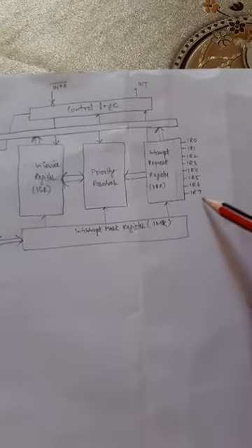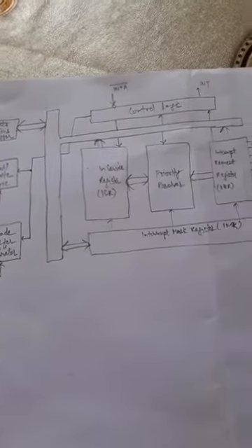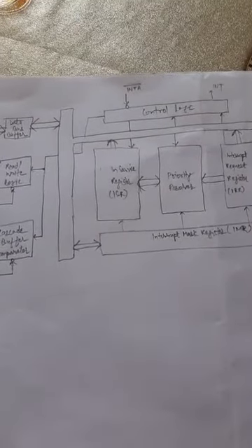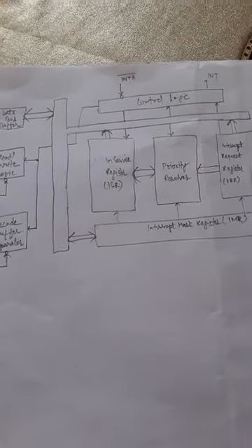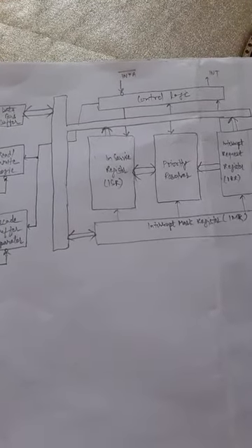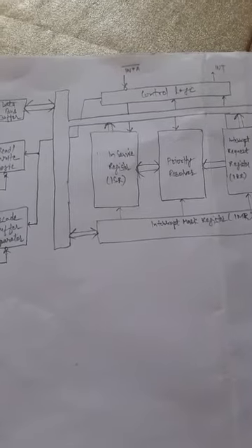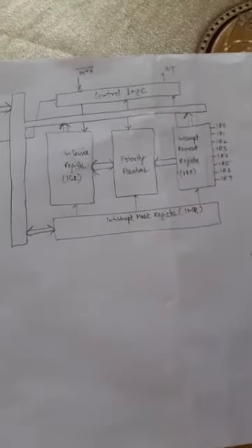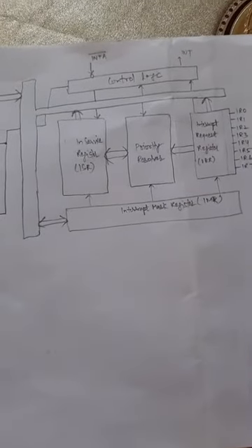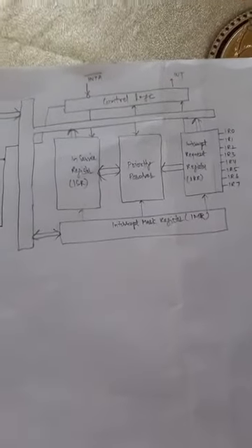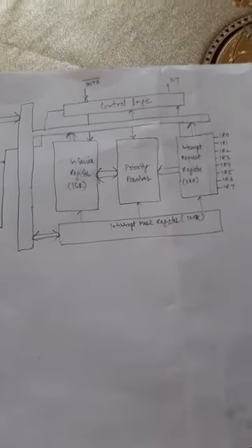The device will interrupt the 8259, and then the 8259 will interrupt the microprocessor. If the processor is interested to service that interrupt, it will send the INTA bar to ask for the ISR address. This was the basic concept; the need for this chip I explained in the last lecture. Now I will explain the architecture of the 8259.